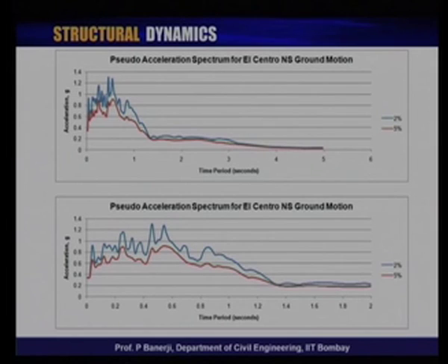Typically, what we give is this, because here there are some specific things which I will talk about in the next lecture. So, the definition of ground motion is either the acceleration time history of the ground motion, or the response spectra of the ground motion. Okay? That is what we have talked about, and once we have the spectra, the reason why the response spectra are better is because we can directly find out the response of a single degree of freedom system to earthquake loads from the response spectrum. Thank you very much.